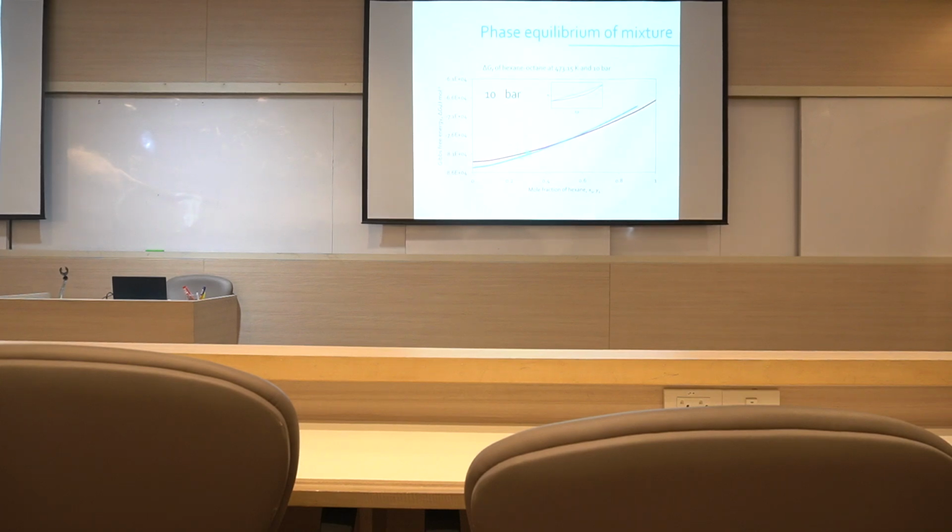However, if you look at this Gibbs free energy diagram, okay, let's apply our previous understanding, which is actually wrong in this case, but let's do this anyway, okay? In our previous understanding, we say our system would try to be in a situation where the Gibbs free energy is lowest, right? So according to this diagram here, in this region to maybe about 0.5, the blue curve is below the red curve. It means the Gibbs free energy of the liquid phase is lower than that of the vapor phase. So your system should be liquid up to where you have 50% hexane in your system, right? And then if you have more hexane than that, the red curve is below the blue curve, it means your system should prefer to be in the vapor phase, right? If you apply our previous knowledge.